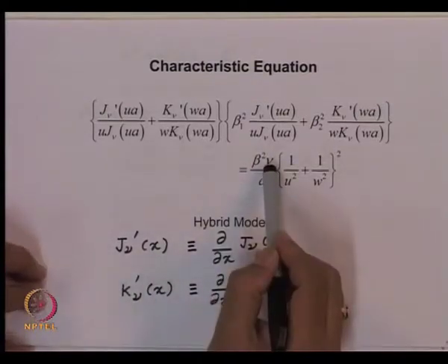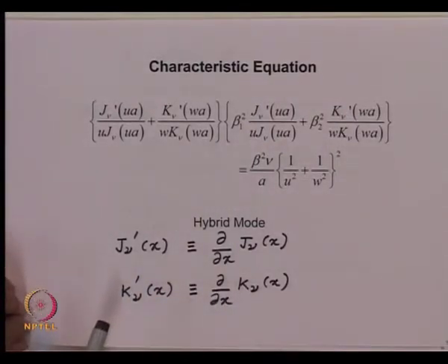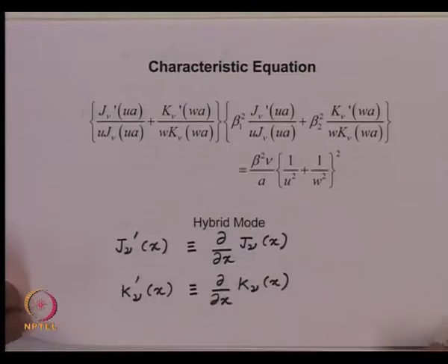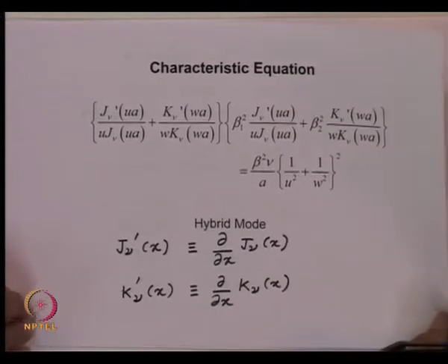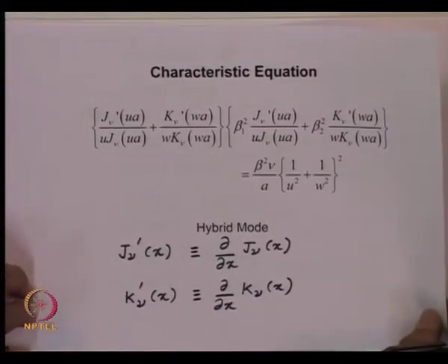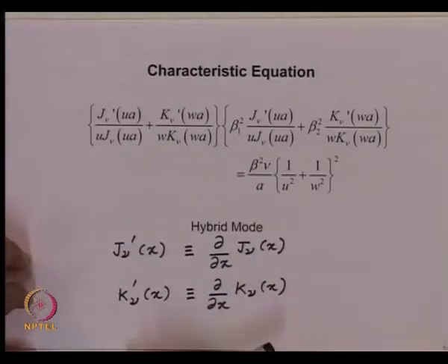And what is nu representing here? The nu represents the variation of the field in the azimuthal direction or in the phi direction, because the functional form for this field is e to the power j nu phi. So we get a variation of electric or magnetic field in the phi direction, given by e to the power j nu phi. If I take nu equal to 0, then that represents a circularly symmetric field, or a field which does not have a variation in the azimuth direction.